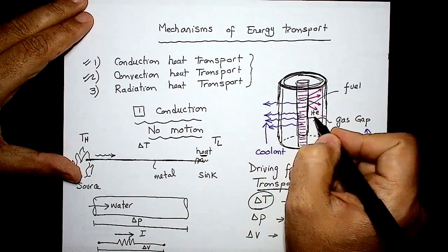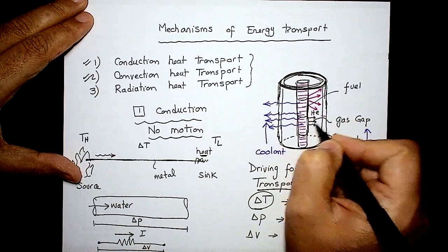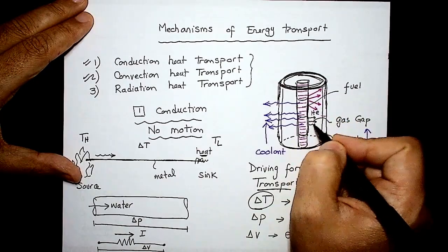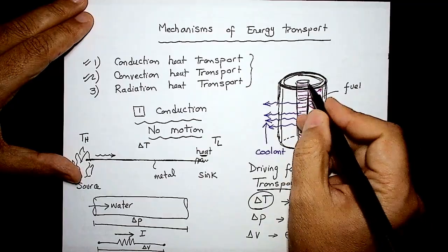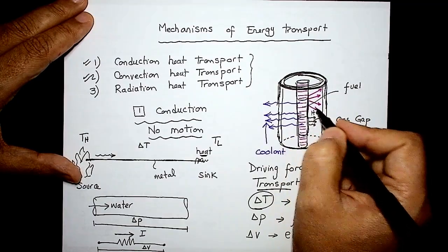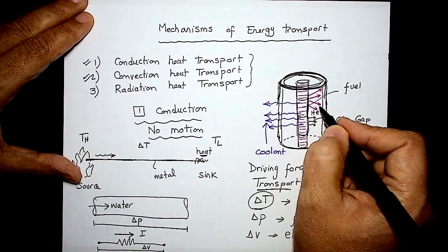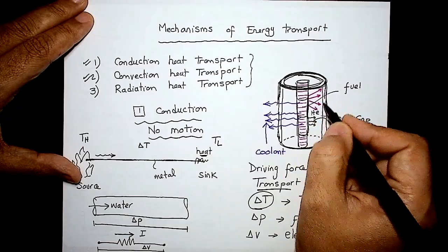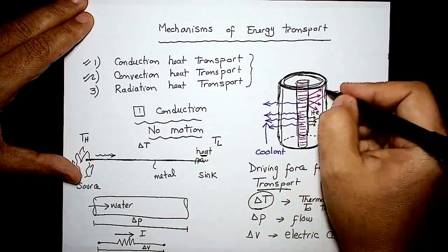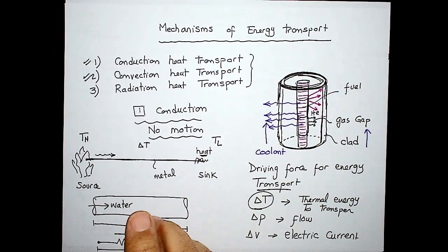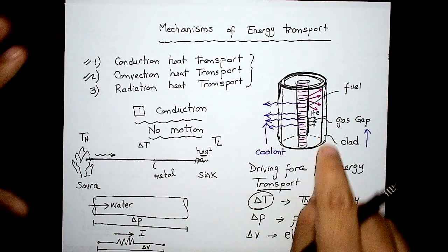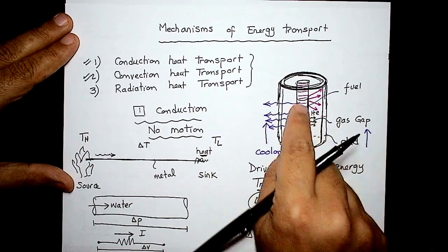There is conduction. Heat will be going by conduction through the stagnant helium layer, but also, because of that high temperature surface of the fuel, it will start emitting or exchanging energy by radiation to the inner face of that fuel cladding. Now, that inner face of the fuel cladding will receive heat by two mechanisms. It will receive conduction and it will receive radiation.